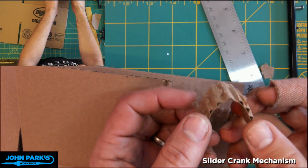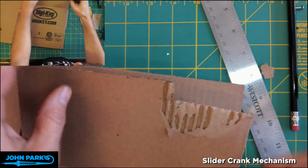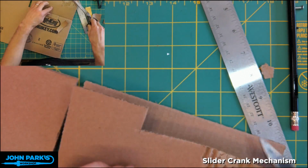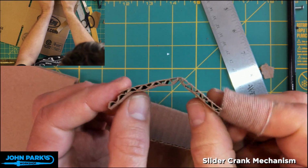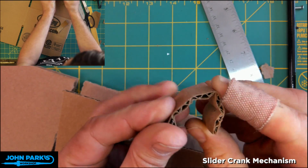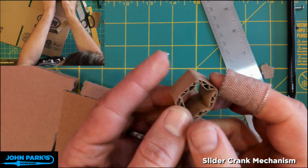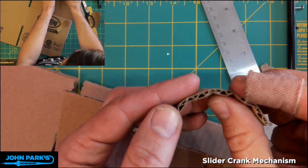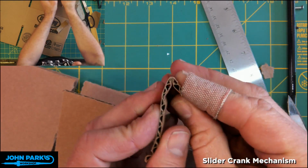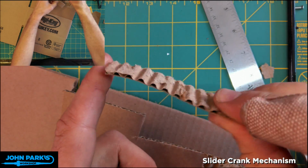But you can see here, if we have a single face and a single wall of this fluting, you end up with a very flexible cardboard. And so compare that to, let's get a roughly equal size piece. Okay, so this now wants to bend along this grain, not quite as readily, and so we get this sort of hexagon shape because of this wall, which has to go somewhere. So you'll see there's a collapse in that corner, and that's something we'll deal with when we're doing more precise construction. But anyway, that does exist out there. You just don't see it that often. Sometimes used as a packing material.